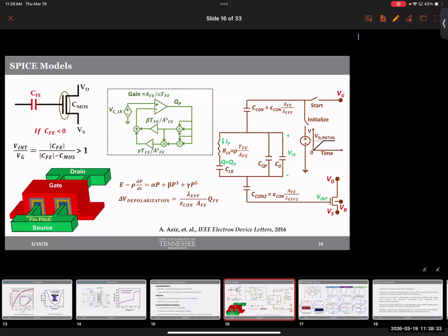Something with some unique features, maybe a ferroelectric, maybe a memristor. You can come up with equivalent circuits to represent those devices. And when you do, you can incorporate that circuit in SPICE, because SPICE is essentially a circuit simulator, right? And you represent the characteristics of that device in the form of a current or voltage, some kind of property of the circuit, typically current and voltage, because the circuit simulators will solve for current and voltage.